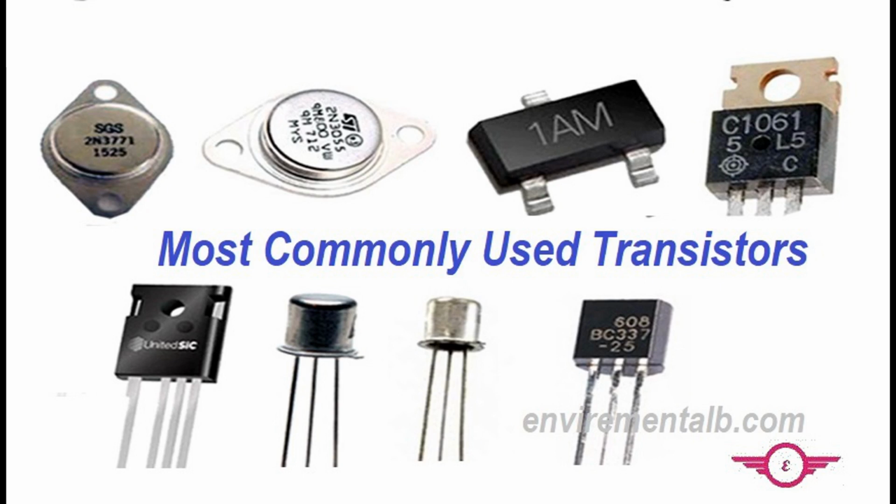The structure of an IGBT consists of a heavily doped N+ substrate acting as the collector, a p-type base region, and an N+ region acting as the emitter. Between the gate and the base region, there is an insulating layer, usually made of silicon dioxide, and a metal gate electrode. The insulated gate allows for voltage control, similar to a MOSFET.